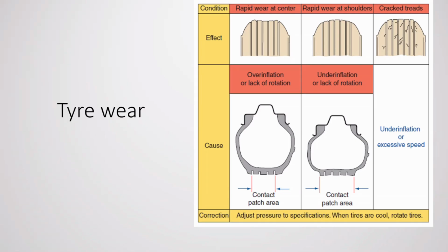The worst case of having cracks is, once you drive with some sort of cruising speeds or highway speeds, there is a possibility of having some sudden failures in tires, especially the crown area, thread area will be wiped out, right? So those shoulders and the crown area will be damaged suddenly.